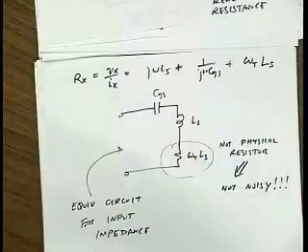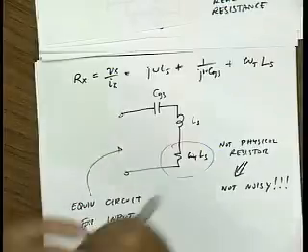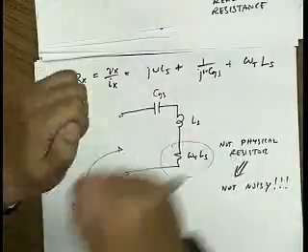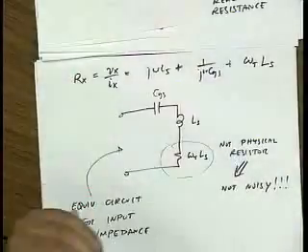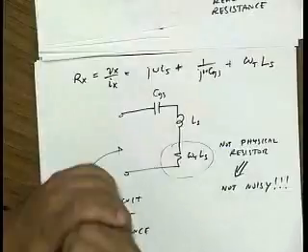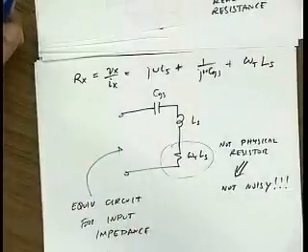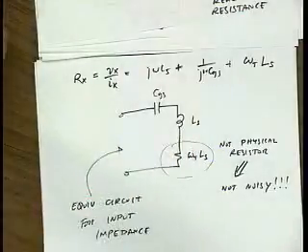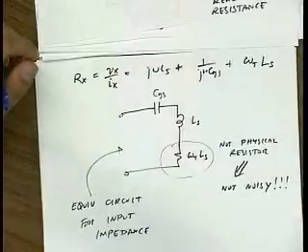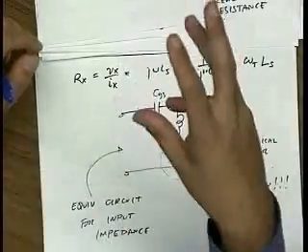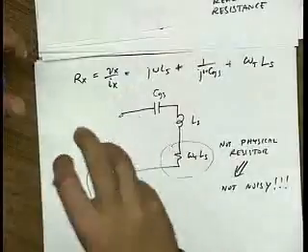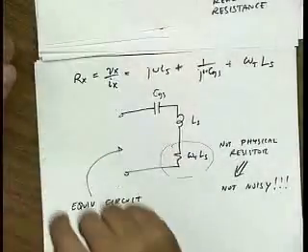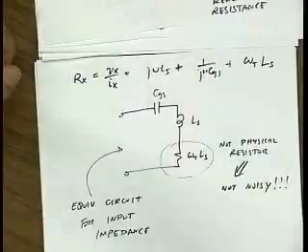Usually, you have to actually run an electromagnetic simulation or do some simple calculations to figure out how big LS is, because it really depends on the package size, the die size, the length of the bond wires, and how bent they are. In fact, you can even go in with a screwdriver and play with that bond wire and change its inductance value. In many designs, you'll need more than a nanohenry to degenerate. You might need 3 nanohenries, in which case you absorb 1 nanohenry from the bond wire, and then externally you place enough inductance to get a match. And you can do that experimentally. You can try different inductors until you see a good input match.